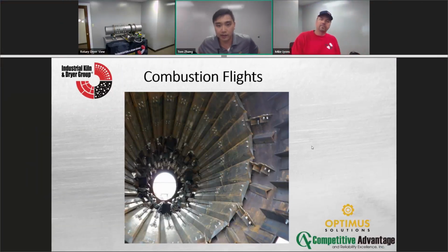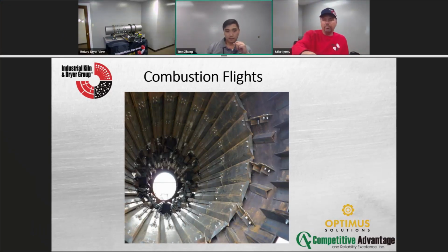Okay, so we talked a little bit about the combustion flights. Actually, you kind of see there, oh, right here. Yeah, that's the angles that you were talking about. And on this one, the kickers are under it, and on some of them, the kickers may be on top of it. So you'll see right here, you can see a little angle there, a little bit of a kicker right there. Okay, so these are typically for direct fire. So if you have a direct heat unit and you don't have combustion flights, then you're kind of missing out and you need to make some changes. But typically, that's not common.